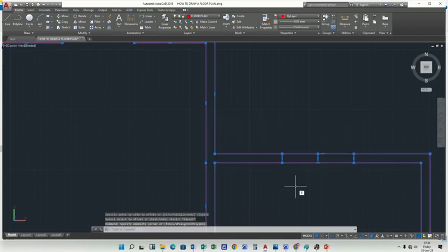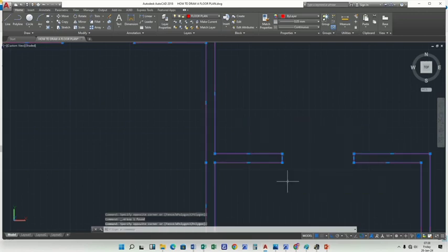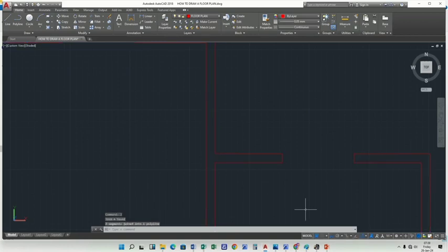Highlight all the lines that are there, and this time I just highlight everything there, then automatically it will delete the other part. Then here I'll just press delete and key in J as a command to join the lines. So the lines have been joined, as you can see. This side is the whole line, and that one is a whole line.